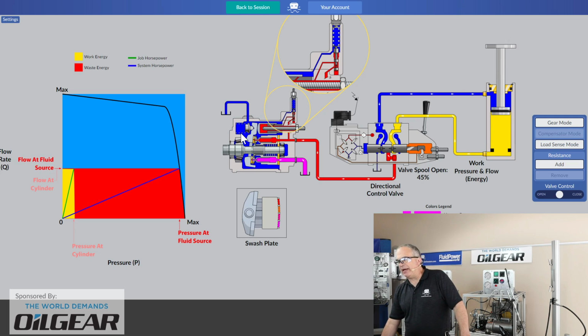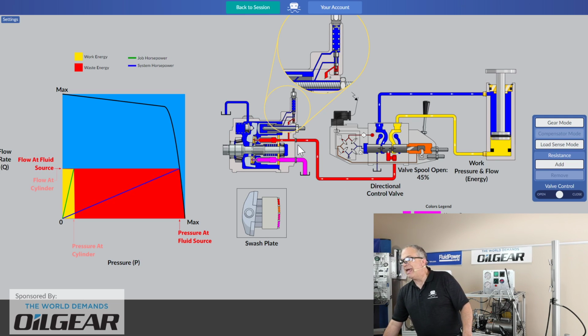The pump comes back on stroke as the pressure compensator closes using the bias spring until those pistons find out that yes, the directional valve, the proportional valve, is still only partly open, and we quickly build up the pressure. So we are here at a constant pressure value, but at least now our pump is supplying only the flow required at the working end of the hydraulics, meaning the directional valve and cylinder.